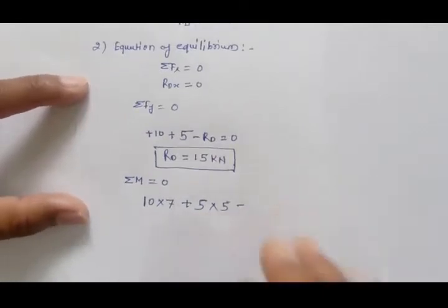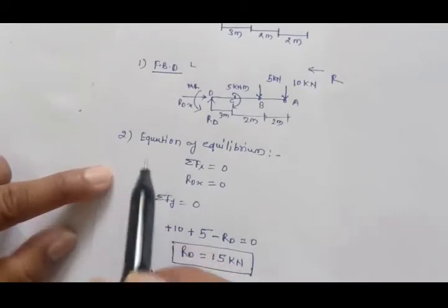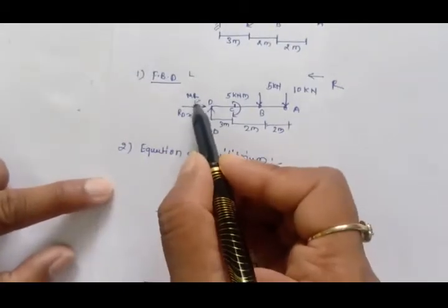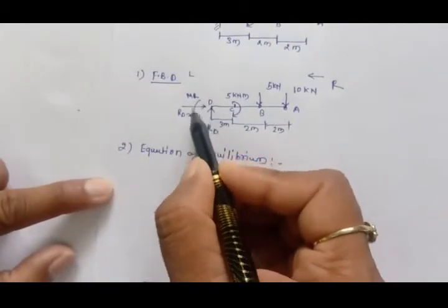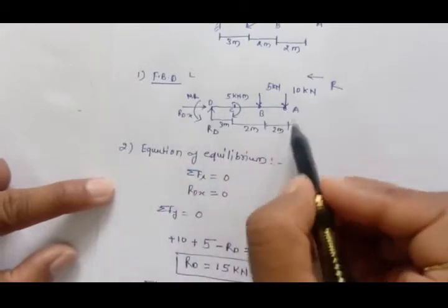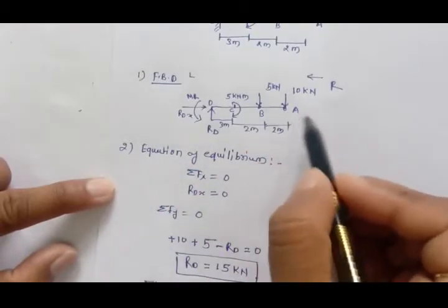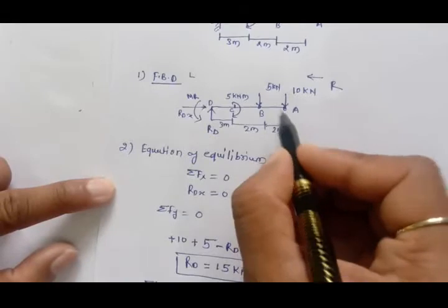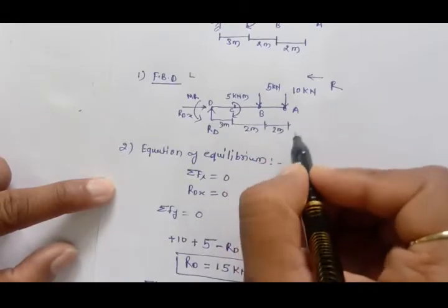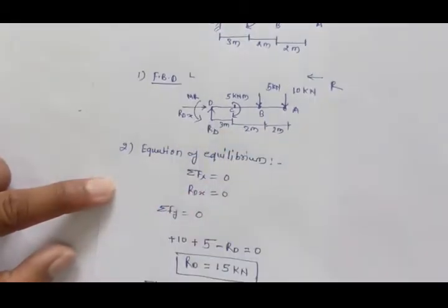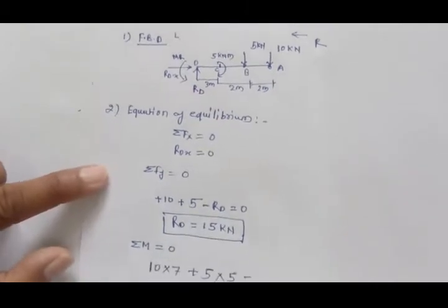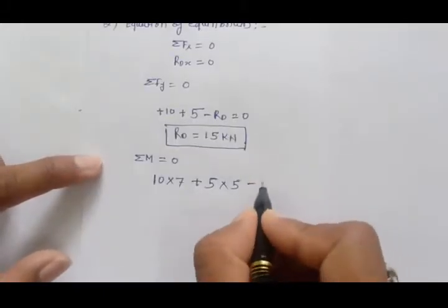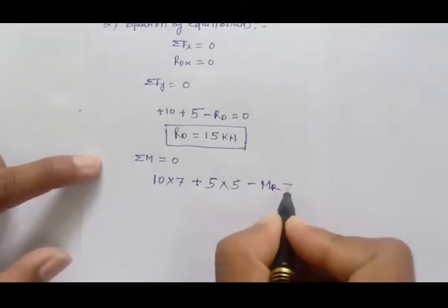and here in this cantilever beam, the rotation is there which supports the beam against going downward, because these vertical forces try to bend this beam downward, so this counter moment will try to resist it. Because its moment is anti-clockwise, we are taking minus MR equal to 0.